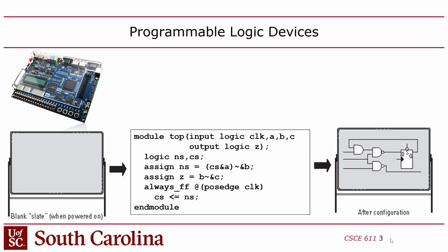So the way you program FPGAs, or the way you design hardware for FPGAs, as well as the way you design digital hardware for an ASIC, like just a regular chip that you fabricate, is through a technique called hardware description language, HDL. It's a high-level programming language that's used to describe circuits. So it's basically the same thing you did in 212, but it's more readable, more reusable, more debuggable, and it allows you to design much larger scale systems with hundreds of millions of transistors or gates.